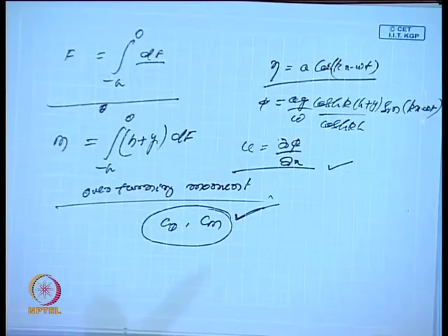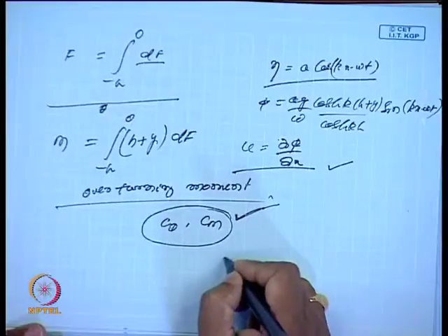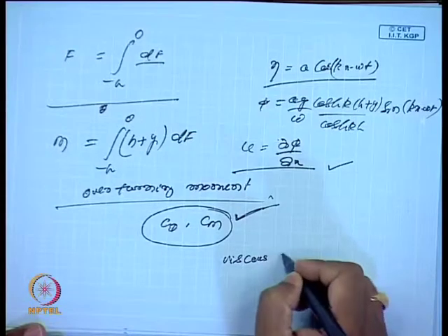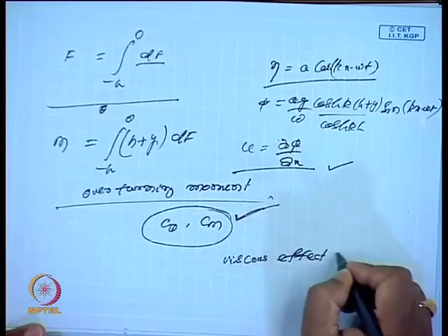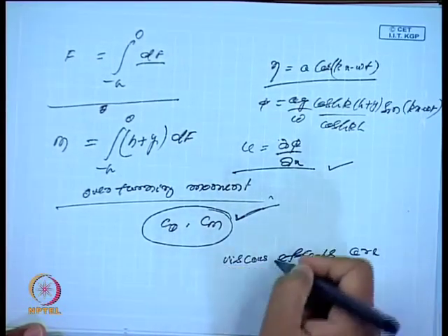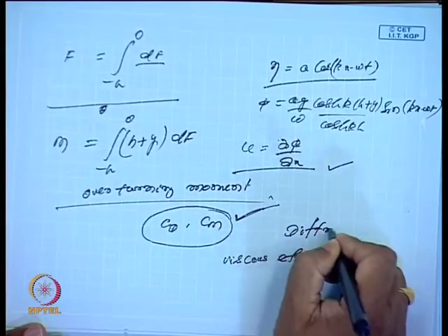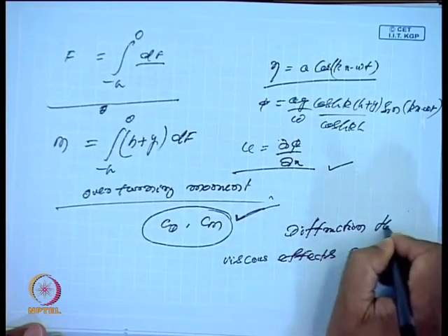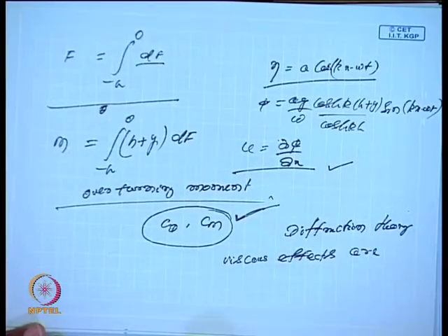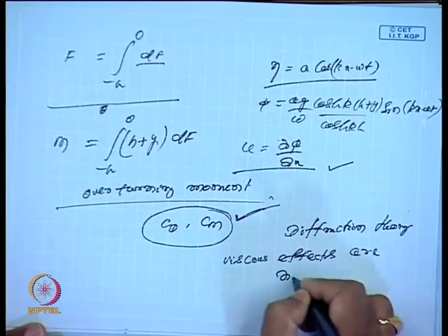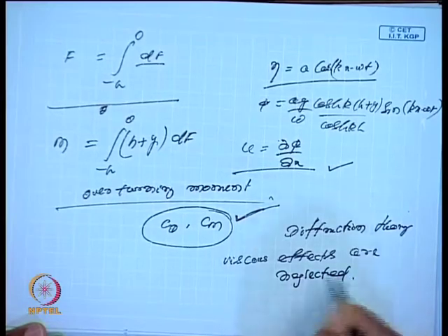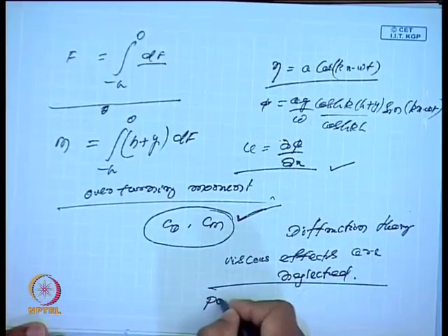On the other hand, in case of diffraction theory, particularly when the structures become very large, such as gravity platforms, we depend on diffraction theory, because here the inertia force dominates and the viscous effects are neglected, and we apply the potential flow theory.